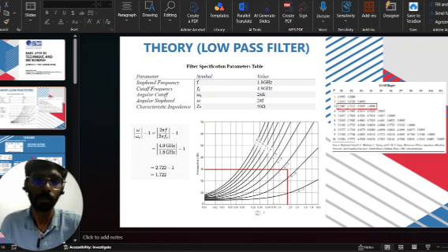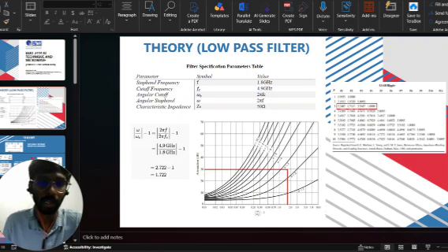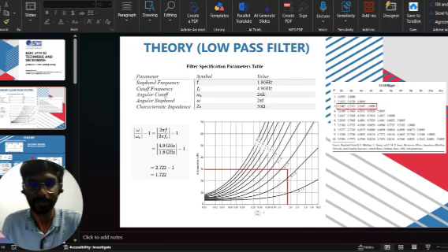Okay. So before starting the design, we determined the specification of the low pass filter. The low pass filter was designed with a cutoff frequency of 1.8 GHz, 30 dB attenuation at 4.9 GHz, and 3 dB Chebyshev equal ripple response. Based on the attenuation curve, we selected a third order filter, which provides a good balance between filter performance and filter circuit complexity. Okay. So here are the calculations that we made for it.